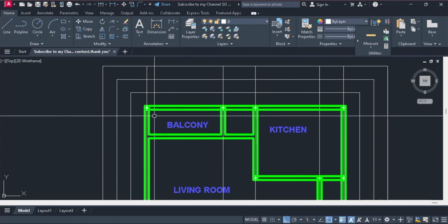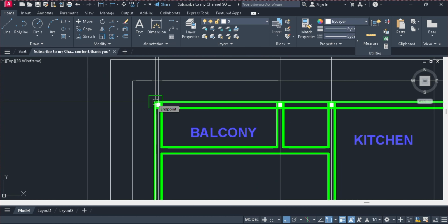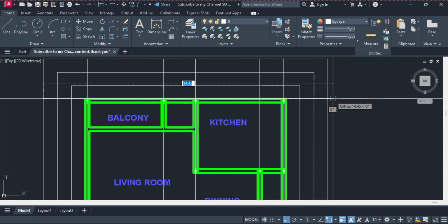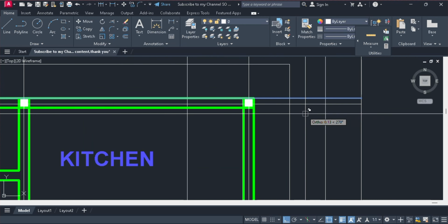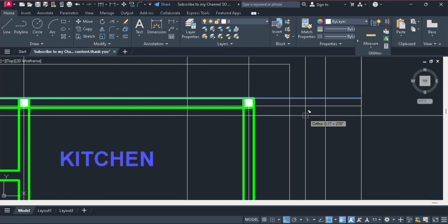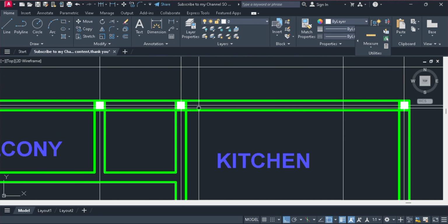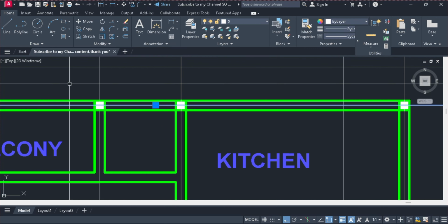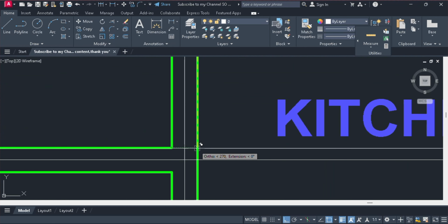For the horizontal axis lines, we'll click on the line tool and choose this base point here and start at this point. We're going to draw through to this other point. The center here is 0.1, so we're going to type in 0.1. We delete the initial line and we are going to copy the line from here. Click on copy. We are going to paste it along the walls, so we'll paste it here.